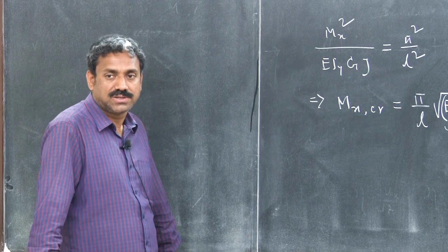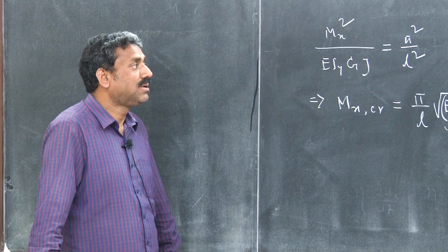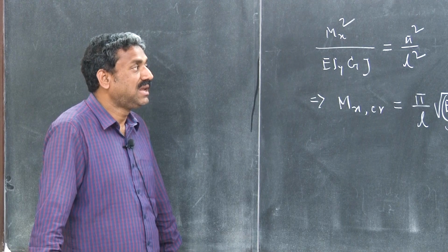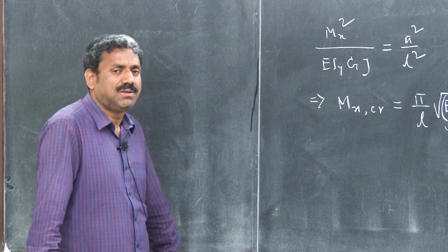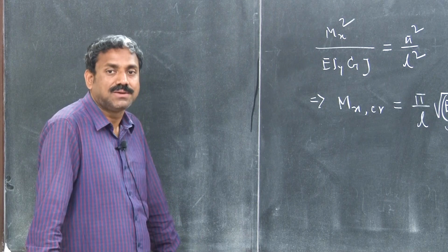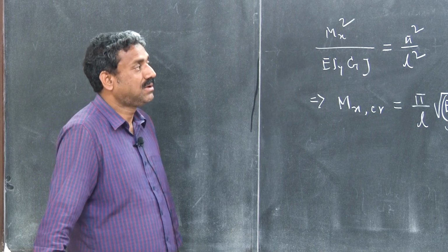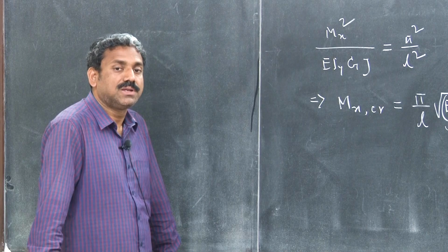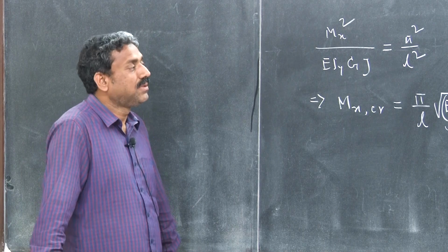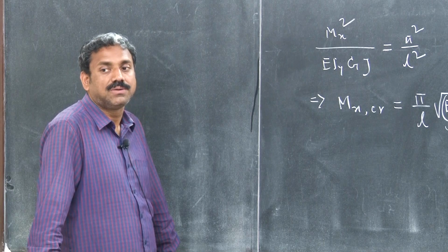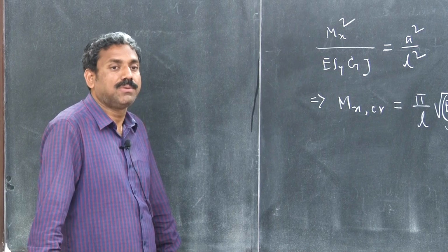Because it leads to a transcendental equation, right? Okay. And then we have considered the elastica, finite deformation of a column, to demonstrate that a column hardly has any post-buckling, post-critical strain, and then we have demonstrated the behavior by considering where flexure and torsion are coupled. So we have considered the torsional flexural buckling of a column, and we have considered lateral buckling of a beam.